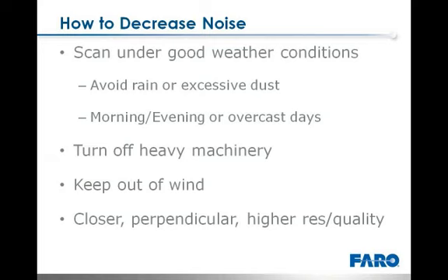For shiny surfaces, try to get as perpendicular to the surface as possible. The more acute the angle, the more light will reflect away instead of return. Also, try turning up the quality and the resolution and get a little closer to the object. Getting closer and having a high resolution and quality will help for dark surfaces also. If these things don't work or aren't possible, we will then turn to filtering.